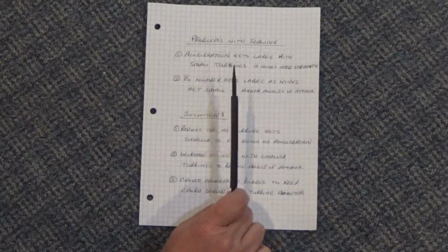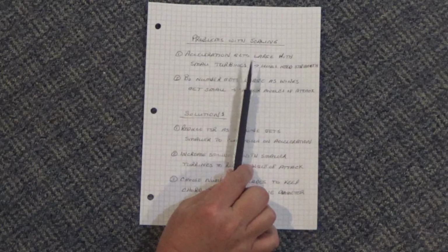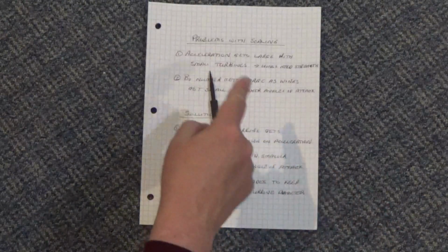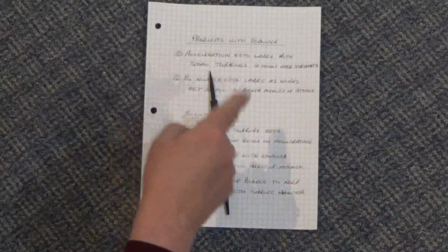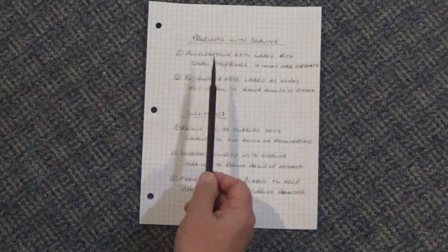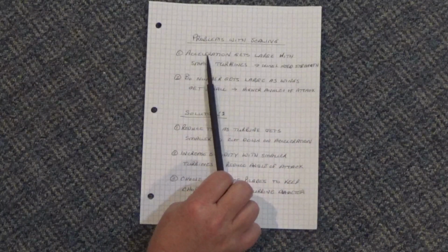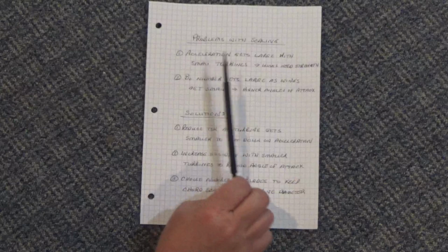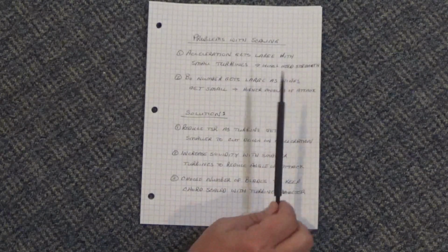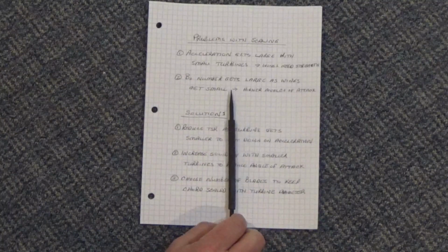So what's the problem? Well, as you get to smaller turbines, the acceleration gets really large. You're going in a small circle, and if you want to keep that tip at a certain tip speed, you get some very high RPMs, and then the acceleration goes up with the RPM squared. And so you get some high accelerations with small turbines. And so your wings need to be strong compared with their mass. They have to be pretty rigid so that they can handle the RPM.